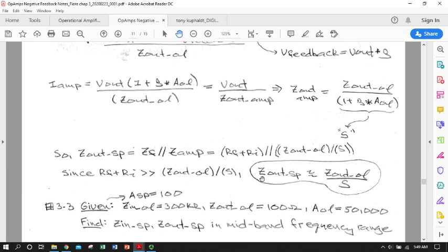So our closed loop series parallel configuration, remember there's 3 other configurations of negative feedback closed loop, but this one's series parallel, we just derived, is going to be approximately equal to our open loop output impedance, findable on a spec sheet, divided by the sacrifice factor. Hey, that was what we wanted.